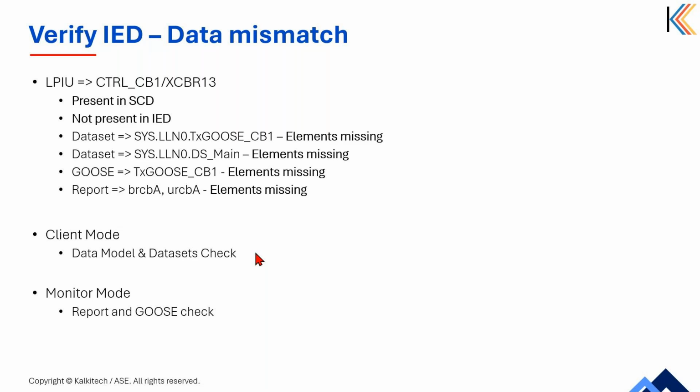That's what we are targeting. If you have any problems in the network, you can hook up the BNET hardware and look at all the sample value streams that you have problems with. You can select the respective devices from the SCD file and start looking at those sample value streams rather than selecting all.